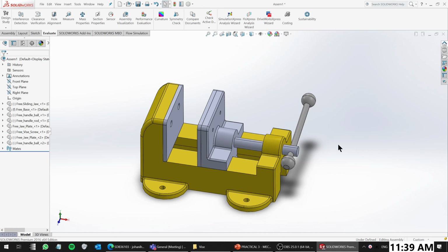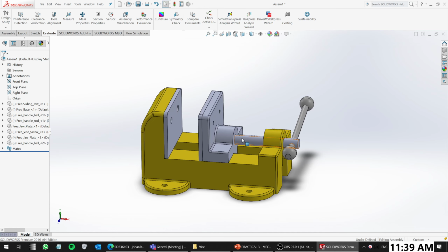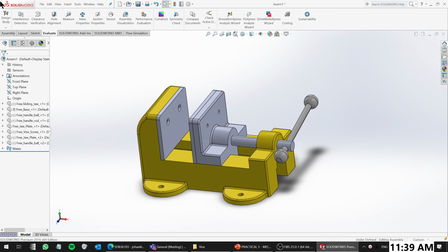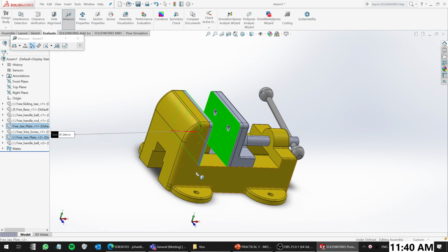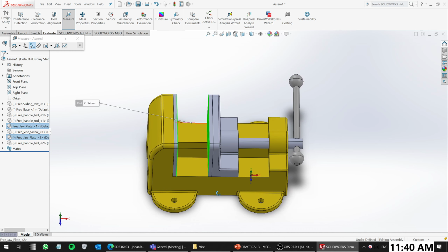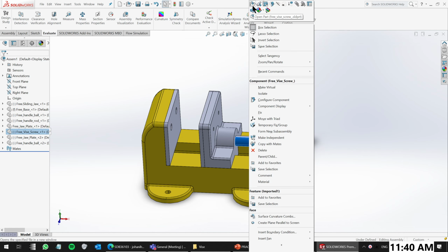But before you open part, obviously the modification that you need to do is make sure this thing is longer, right? So elongate the part. But how long? Choose evaluate, click measure, this surface to this surface. The distance is about 42 mm, so you need to modify at least by adding about 42 mm. So go to the part, right click, open part.